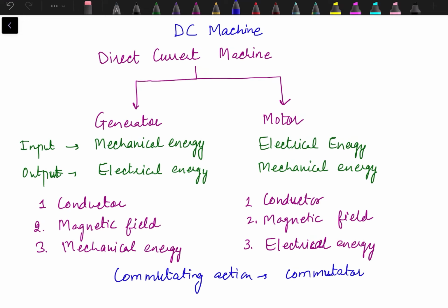If we talk about the generators, the DC generators are not common, or we say that they are rarely used, because we can easily avail the DC supply through electronic rectifiers. With the advancement in power electronic devices, we have converters available in different sizes, and we can easily avail the DC supply from the AC only.